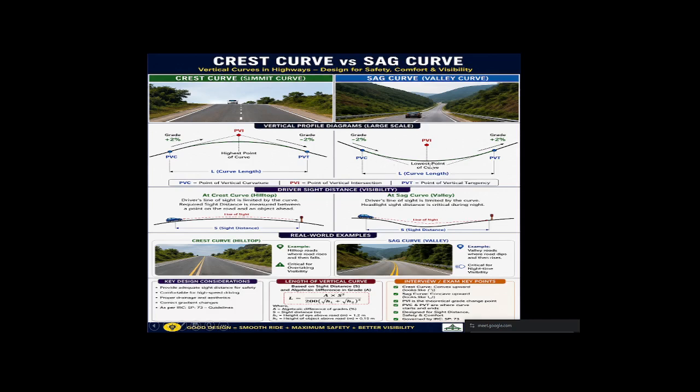In Civil 3D, the curve is created automatically when we design a profile. I already showed you that when you create your profile with the help of the tangent tool, the curve is created automatically. There is also a different tool, which I will show you after this. If you don't want a direct curve, you can manage your curve as per your own direction.